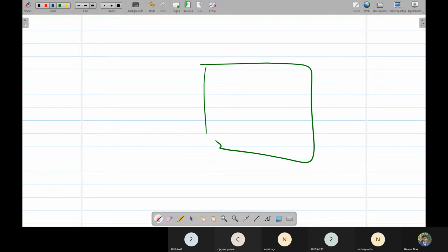The second part of the circle is a very small part, so it is only the line of base plate. Base plate is, for example, this is a concrete pad. You have to place a column on top of it. We cannot place the column directly, so we place a steel base plate on it, onto which we fix our column. We weld this column to this base plate. This base plate is anchored in the concrete pad. Why do we use the base plate?